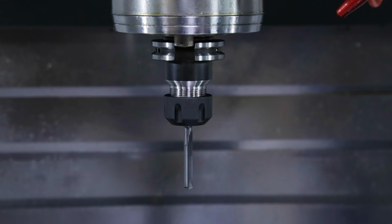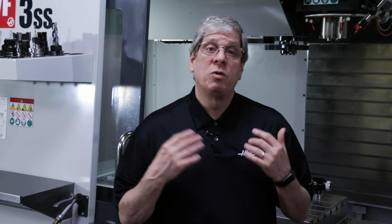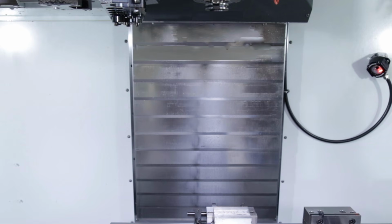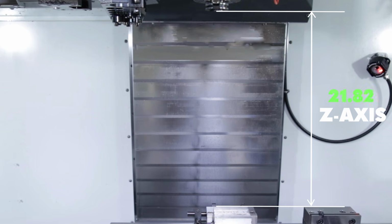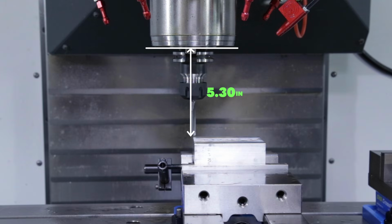Here's the cutting tool we'll be using right now. The tip of this tool is exactly 5.3 inches from the face of the spindle. This is our tool coordinate, or tool offset as it's most always called. In our example here, with the Z-axis at home position, our Z-axis work offset is minus 22.73 inches from the face of our spindle to the top of our workpiece. And our tool offset for this cutter is 5.3 inches below the face of our spindle.